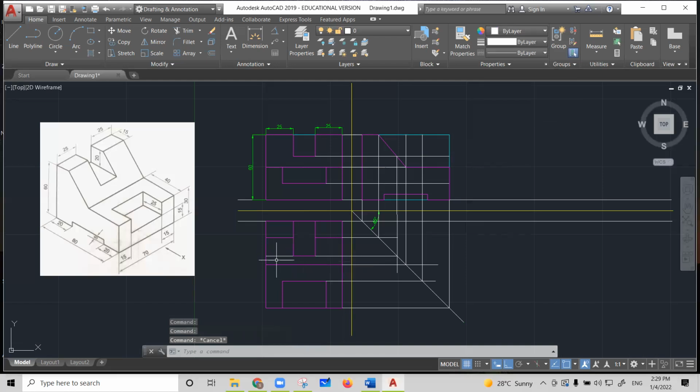So this will be the slot which I have mentioned here. This slot visible in top view will be up to this line, and this reference you are going to get from this intersection projection line meeting this inclined surface. So accordingly you will project it, get it in a top view and complete this one.